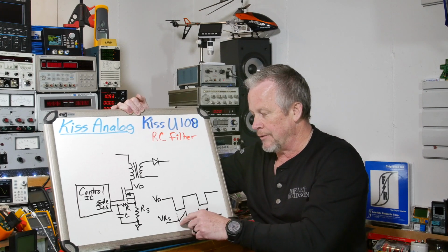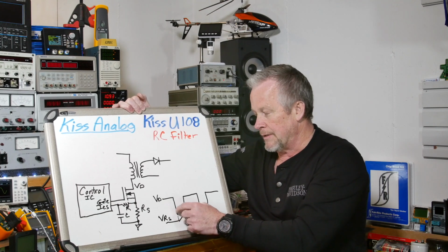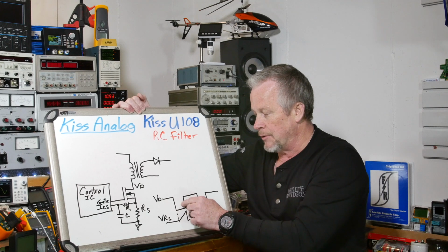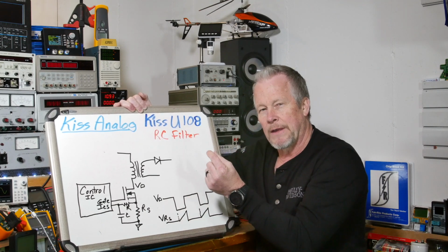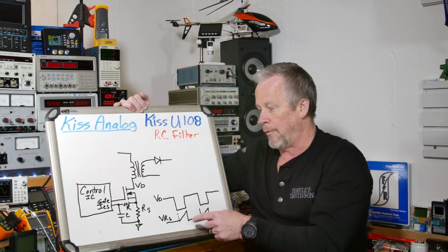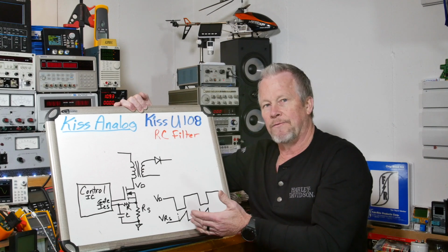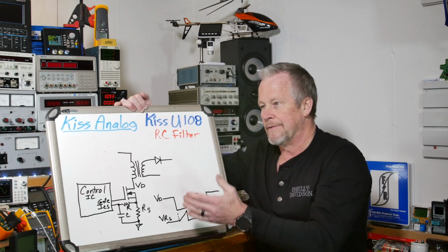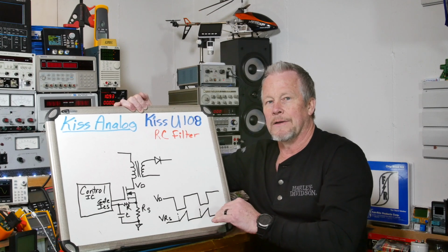So basically you don't really care about what's happening here, but you don't want that time constant too long, because that'll limit how narrow the pulse width can get before the filter starts to give a fake feedback, because the feedback signal it's letting in is lower than what it should be.